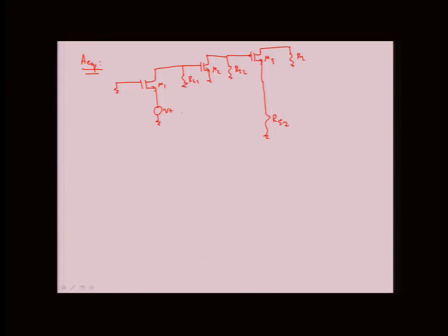Now, what I'm seeing here, I have RF, RS1, and then whatever VT is seeing, which should be, let's say, 1 over GM1, I'm going to terminate here, and I'm measuring VR, right? So this is our standard return ratio thing. So let's make this first, just so it's not confusing, return ratio.